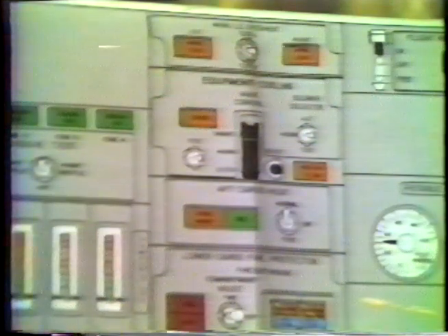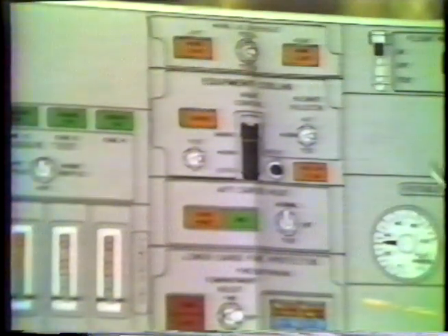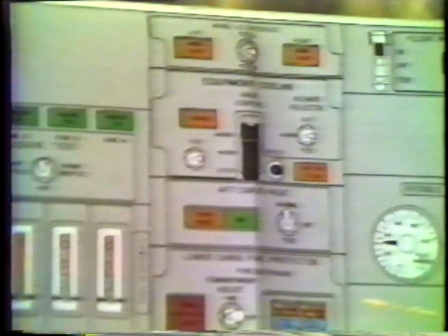As a matter of fact, the entire forward cargo's only heating source is this air. Now there is some air going down along the sidewalls from the conditioned air from the main deck. However, the primary source of heating of the forward cargo is this air that's going across the equipment.